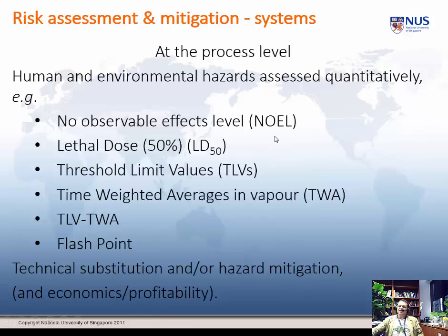You need to have the no observable effects level. That is the level at which there are no effects that can be observed with people. You need the lethal dose, the LD50, the lethal dose at which 50% of the population will die if they're exposed to that level. You need threshold levels. You need time-weighted averages of concentrations in the vapor phase. You need the flash point, and